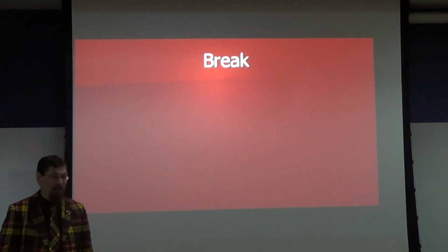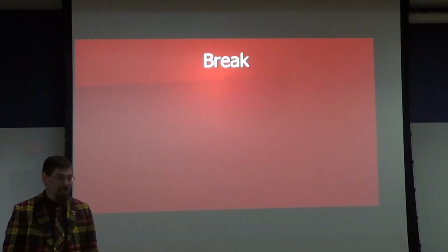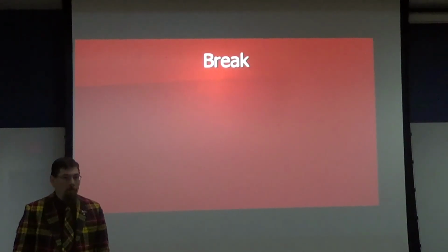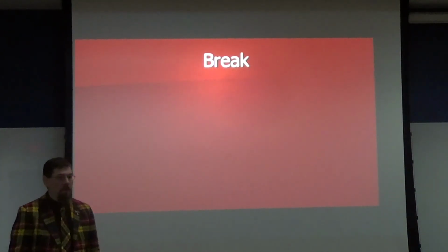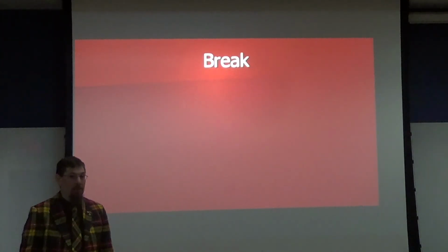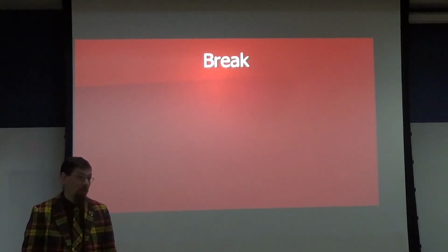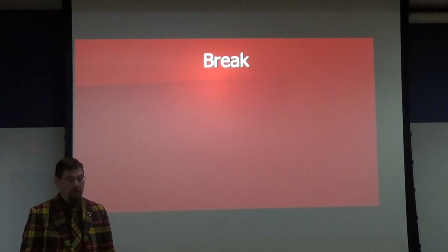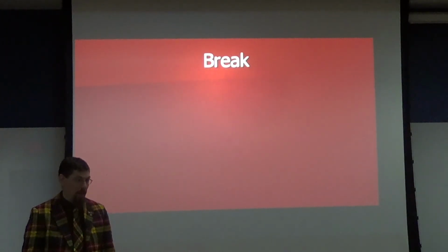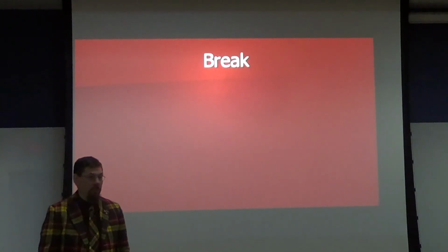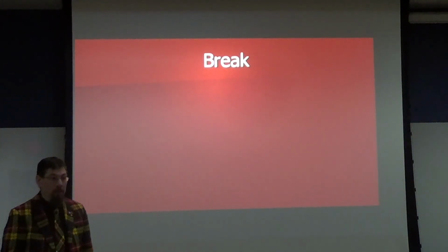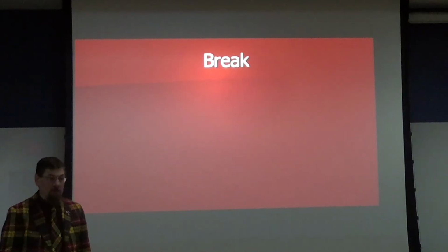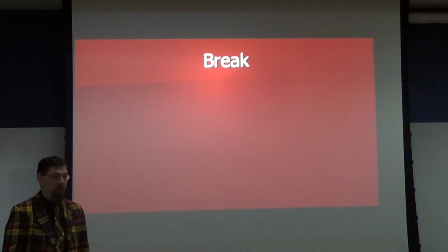How does grain size compare to castings or forgings? I know they're really long, but are they similar to really small refined grains in castings? So the actual grain size is going to be very small. Typically, grain size is measured on an ASTM grain size scale. In the world of forgings, you're typically going to see requirements for the grain size to be 5 or finer, 7 or finer, and it's not unusual to see them much smaller than that. But those are typically what customers are going to require.